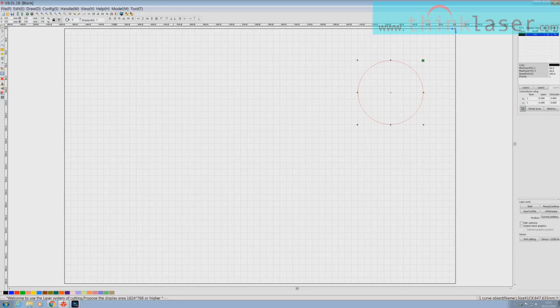Well, if you look, the clue is in the scaling at the top here, because the scaling for this drawing is working away, as I said, from 0, 0. So it's running backwards. It's not running from this corner as you might have expected. It's running away from this 0, 0 point, and it's running down the page from that 0 point at the top.